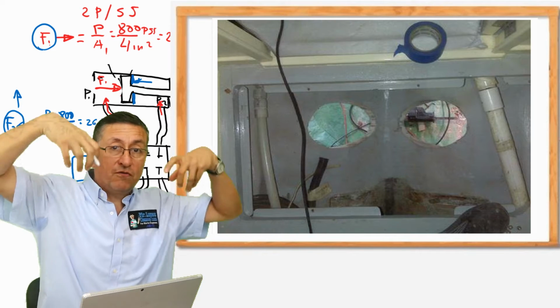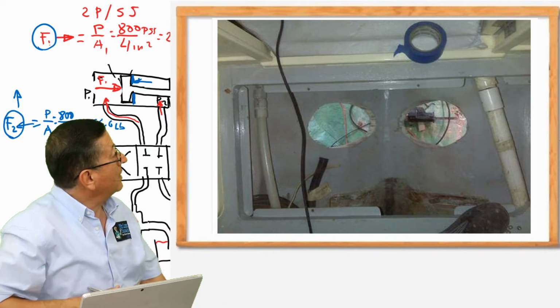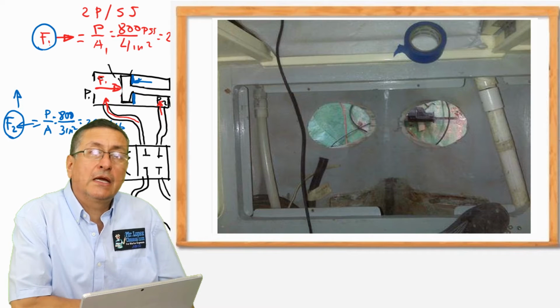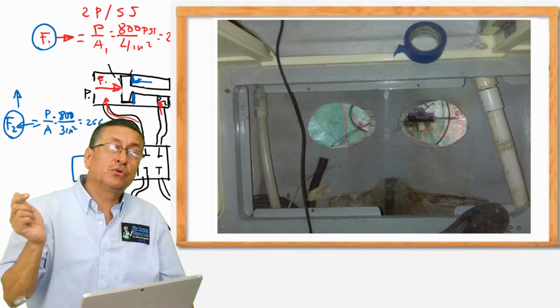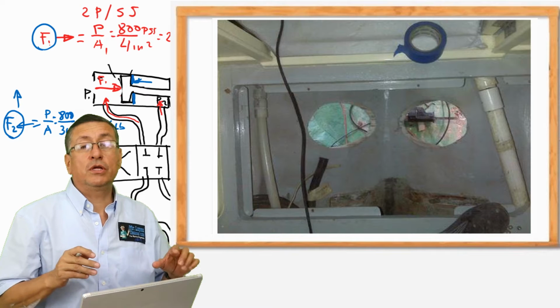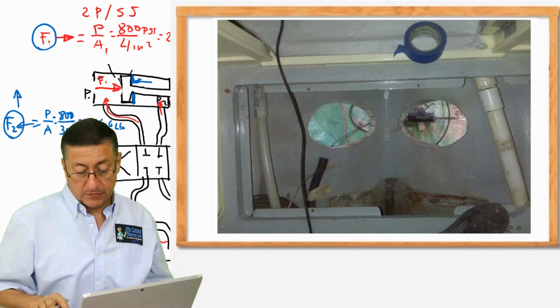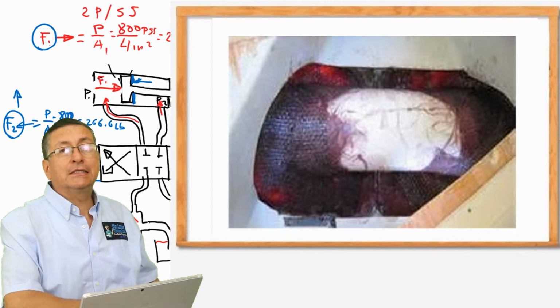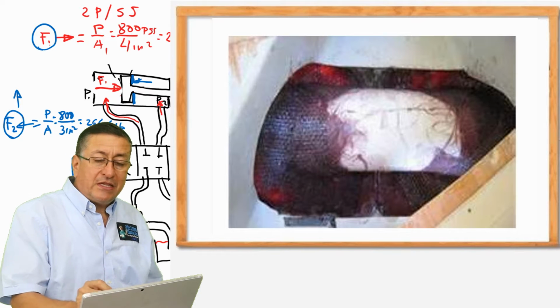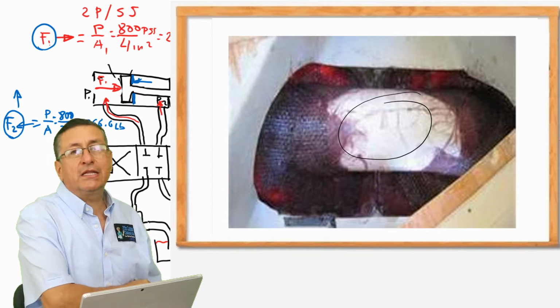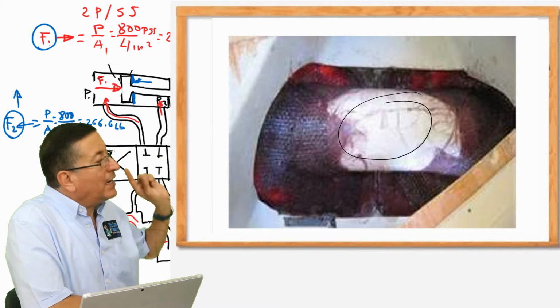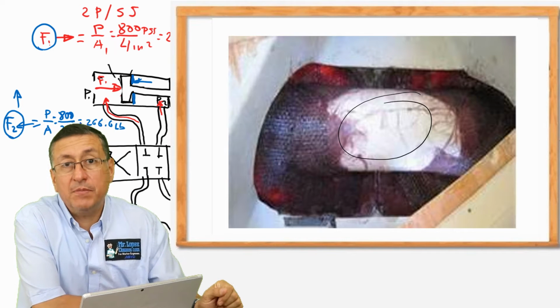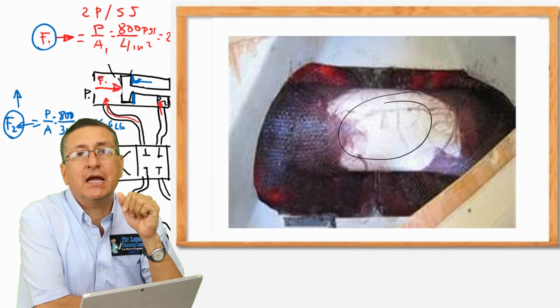Alright, this is the hull. If you check the hull from inside of the boat, that's the hull. And now we are going to introduce the tunnel, and we are going to laminate on the edge. Exactly like this. Be careful with this area. Keep that area clean, my friends. Believe me. Keep that area clean.